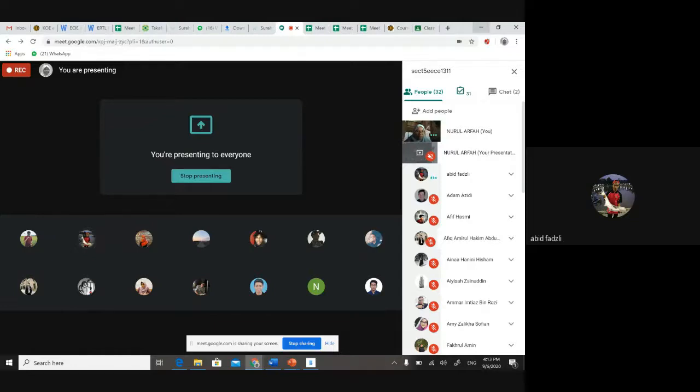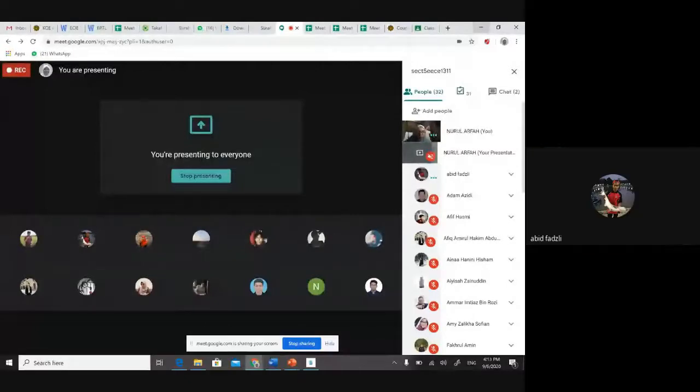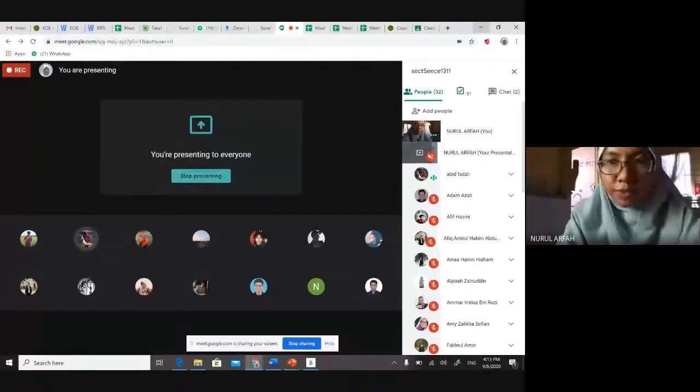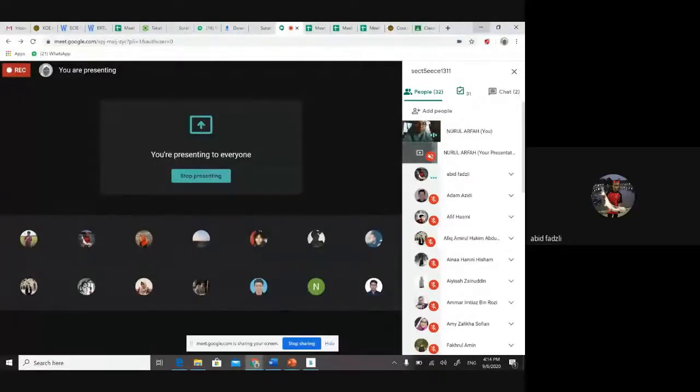Madam, for nodal analysis, if there is no super node, we just use KCL. Yes, use KCL if there is no super node. For mesh, it is the same, we use KVL. If it becomes a super node or super mesh, we can use both. If you don't have any super mesh, you also use only the normal mesh. Oh, okay. Thank you madam.